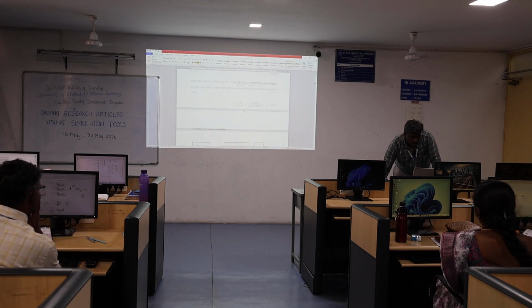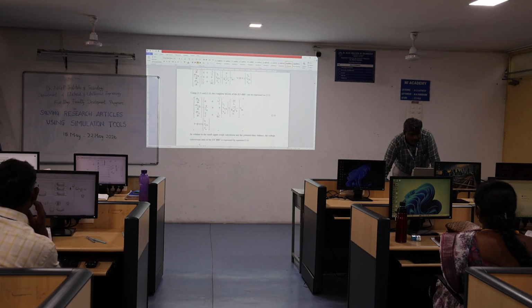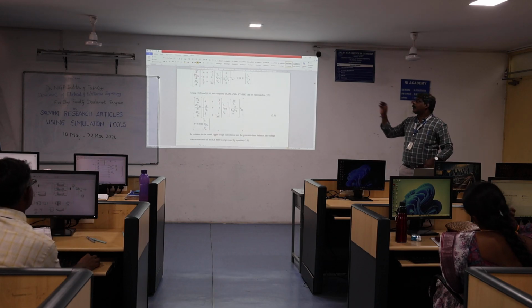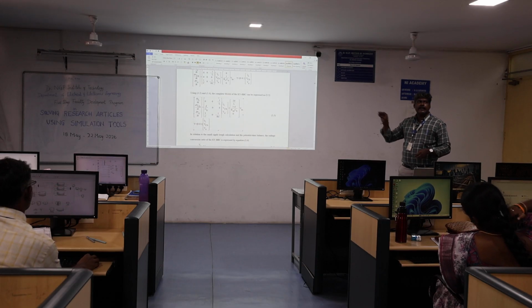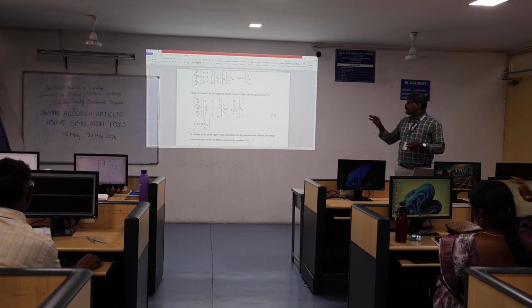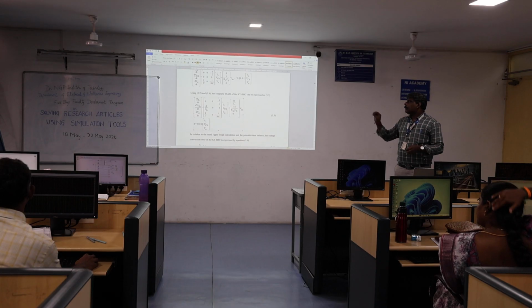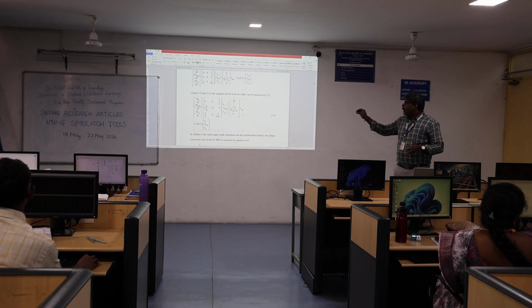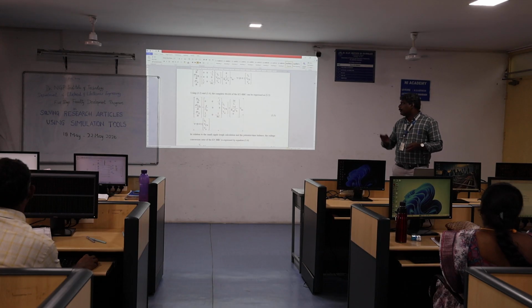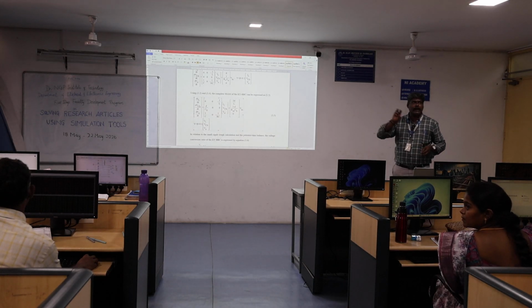So in this model you have to substitute the L value. For example, L value is 200 microhenry. Then duty cycle is 0.5; we are going to choose a duty cycle of 0.5. Capacitor value some value. Then R value, load resistance value, maybe 50 ohm. Capacitor another value, some other value. You just substitute, you will get some numerical data.